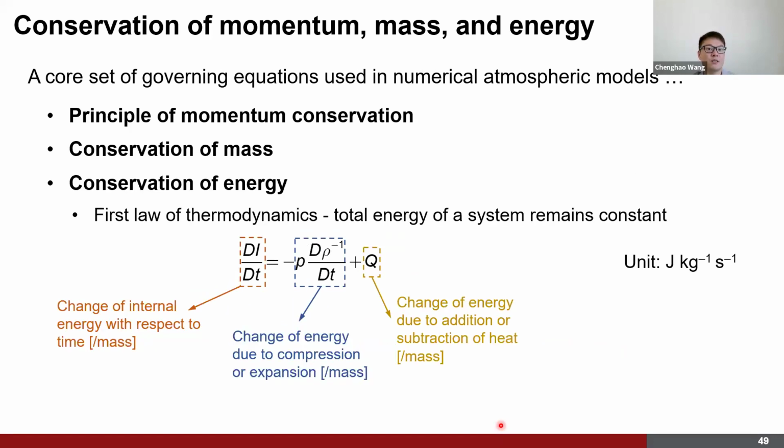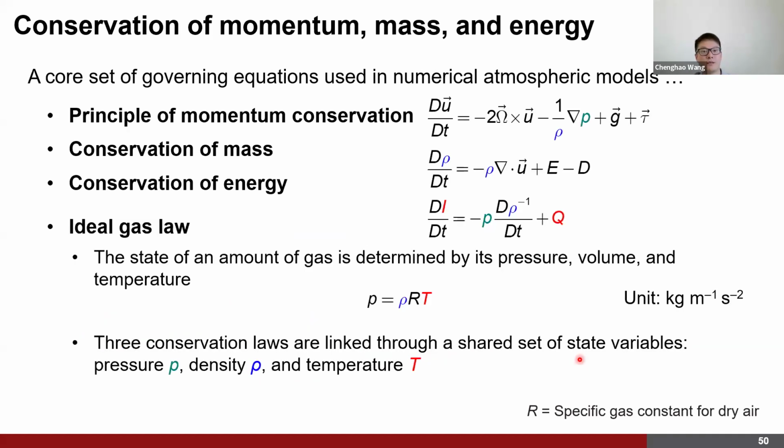And the third governing equation is the energy conservation equation. Here we are using the first law of thermodynamics. Energy can neither be created nor destroyed. So we have the change of internal energy equal to the change of energy due to compression or expansion, plus the change of energy due to addition or subtraction of heat, basically the heat exchange between the system and the surrounding environment. The last one is just the equation of state, or ideal gas law,